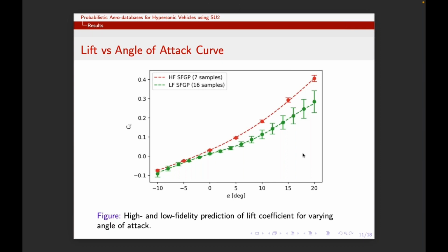And so we can compare the results of our high fidelity, which is SU2, the red line, and then the low fidelity results, which is the SHARP package, the green line. And again, the first key to combine multi-fidelity information is that the data are correlated, i.e. that we're capturing the relevant physics, even if there's bias. And for the large part, we're doing that very well in the domain, particularly at low to negative angles of attack. The Newtonian aerodynamics performs very well. We see that the discrepancy grows in line with the data uncertainty of the low fidelity model as we move into higher angles of attack. But the trend-wise comparison is very similar between the two.